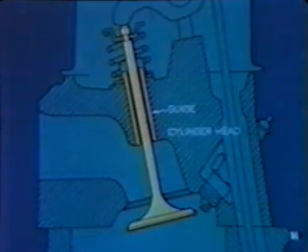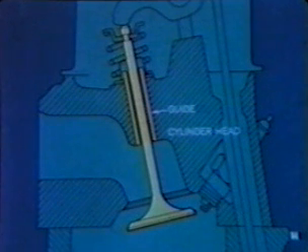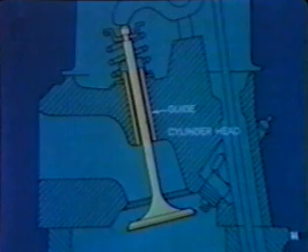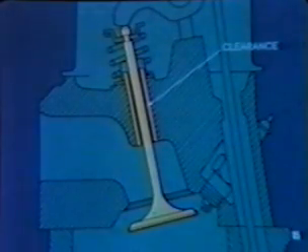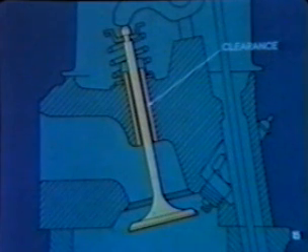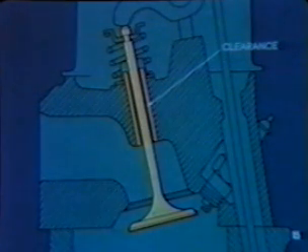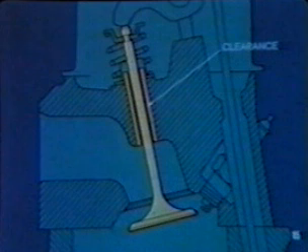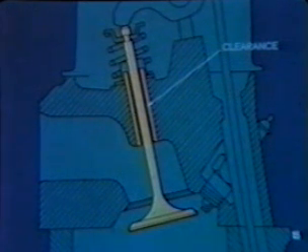Valve guides are usually machined into the cylinder head. In some cases, though, cast bushings are pressed into the head. There is a very close fit between the valve stem and the guide, with just enough clearance to allow lubrication and a slight bit of heat expansion. The cold clearance may be higher for the exhaust valve since it gets hotter in operation.